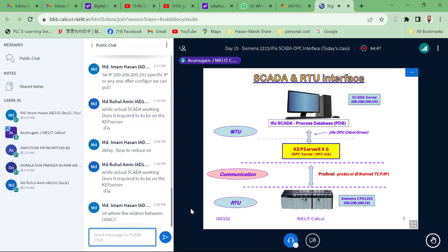Here itself, because in the AA block only, you are assigning the alarms, right? This alarm will go. But from here, if you want, you can store in the database. That also is possible. Through iFix, you go to iFix and send the data to the database, or from the OPC server also, you can send the data to the database. Two methods are there. This one is through iFix. This is direct. That's all. Understood or not?